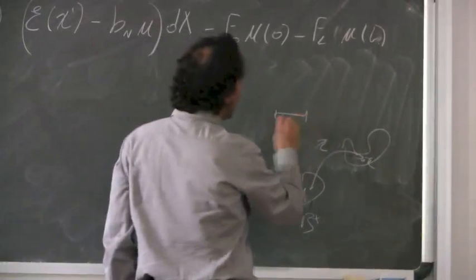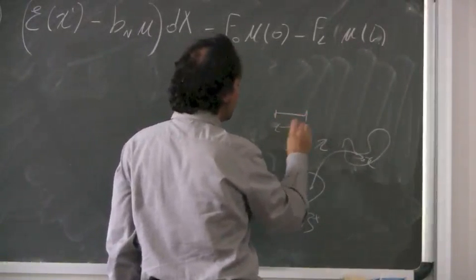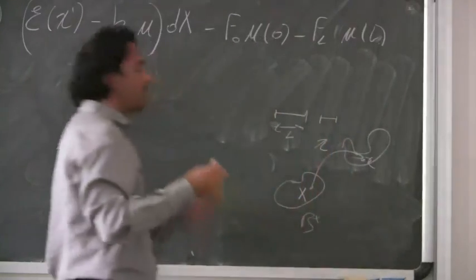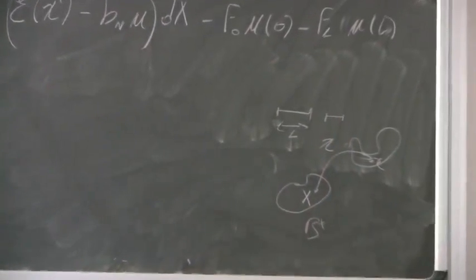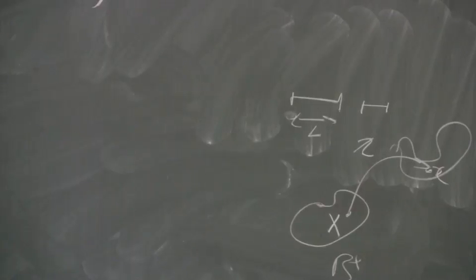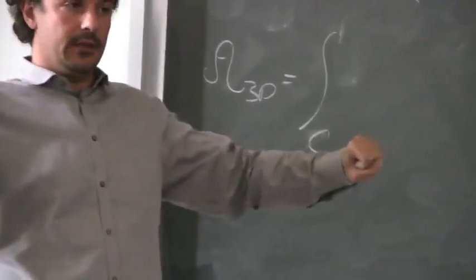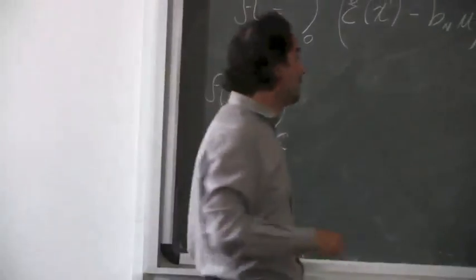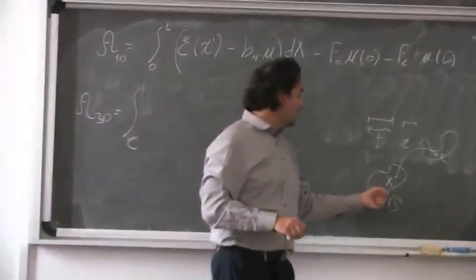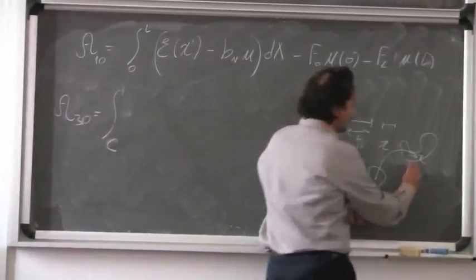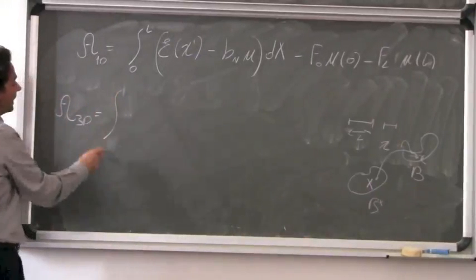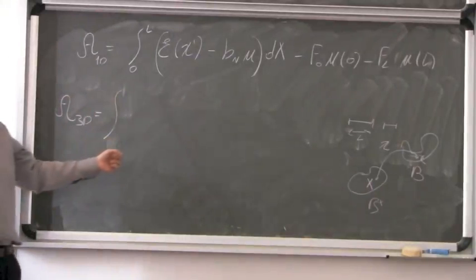Before, we had a bar, the length of which was L, and at the end maybe you have a bar, the length of which, who knows, depends upon the force. If you take an elastic material and you pull, the length is different from the initial length L. But we have used the integral from 0 to L. So here we have a referential configuration and a present configuration. We have to make an integral here in the reference configuration and in the present configuration.